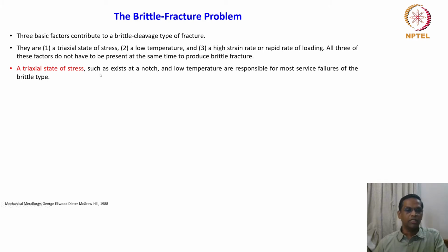A triaxial state of stress such as exists at a notch, because please remember we are making a notch in the Charpy test specimen, and the low temperature are responsible for the most service failure of the brittle type. So in general, a notch, that's why we simulate this notch in this test. So notch is a stress concentrator, right? So similarly, the low temperature, these combinations, or it could be either individual or a combination, is responsible for most of the failures.